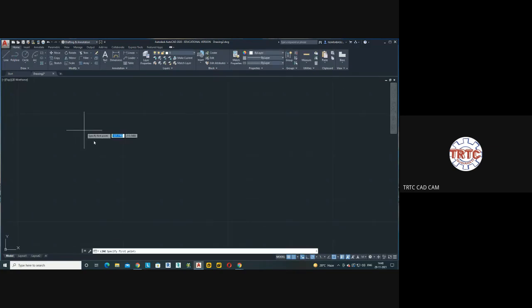Now what happened? If I make an angle, after hitting the first point, if I take my mouse up, see, whenever it is getting 45 degrees, my length will become 100. Next multiple of 45 will be 90. You can see the length: 75, 77. If I move it to 90, see, it has become 100.